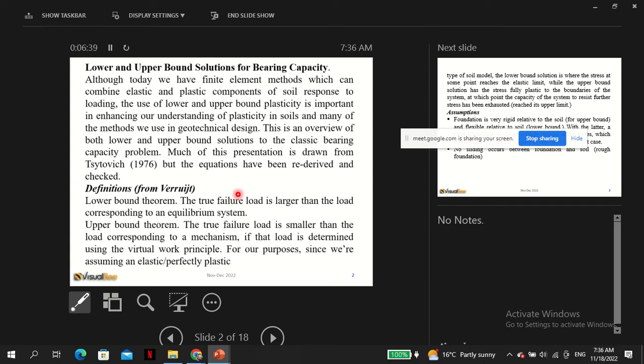The higher the degree of uncertainty, the higher the factor of safety. So initially we said 2.5 to 3, but in reality we apply 3 to 6 for actual design out in the field, because in the methods of determination there are some levels of uncertainty.